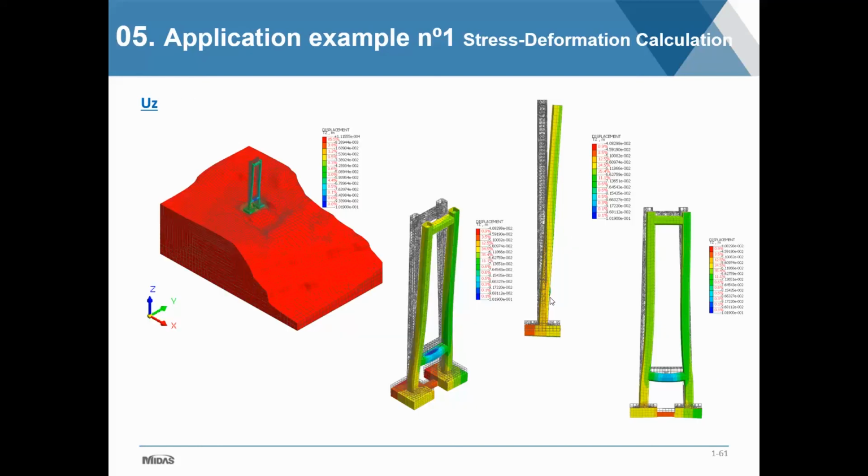And then lastly, the vertical load applied directly here in the pier. We're seeing here about 4 centimeters maximum displacement in red, and then about 10 centimeters in the blue. So positive being up and negative being down. So it's about 10 centimeters would be like here.